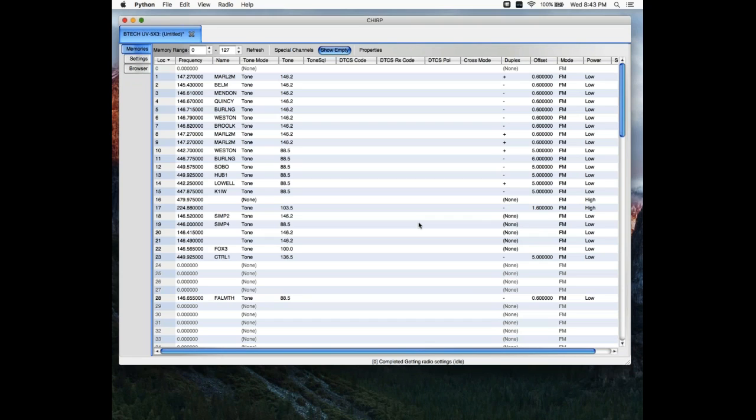Let me give you an alternate. One of the great things about these little FTDI boards that I use is they have that TX data pin next to the RX data pin, and you can connect a jumper wire between the two of them. Then you can open up HyperTerm or CoolTerm or Minicom or whatever your favorite terminal program is, and if you type letters at it and they come back at you, then the driver's working and the chip is working and everything's working out to that end of the board.